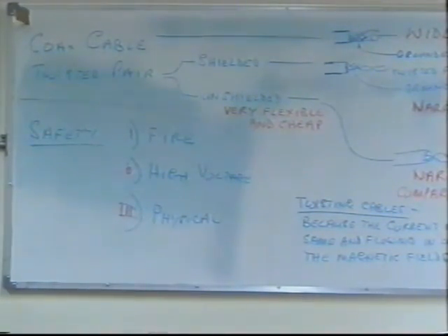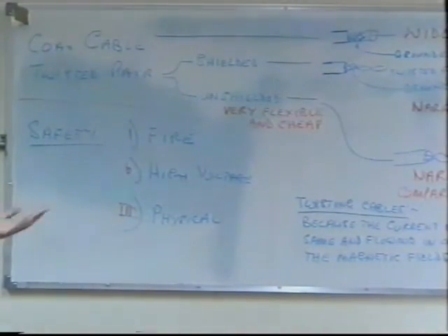But imagine a situation, God forbid that this ever happened, where you can see the guy, he's still got the electricity connected to him, but you can't find immediately the power switch for some reason. Then you've got to try and get the guy off as quickly as possible, by wood, and hit his hand. Well, obviously, it's no use you going to touch him yourself because you're going to end up in the same position. So you've got to use something to push him away. But I don't think that's a practical sort of thing you've got to bear in mind.